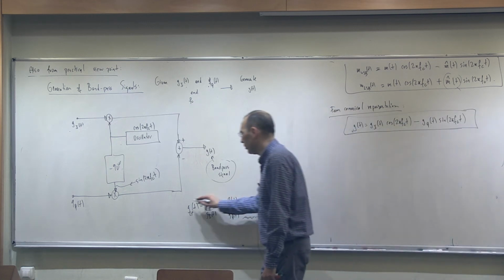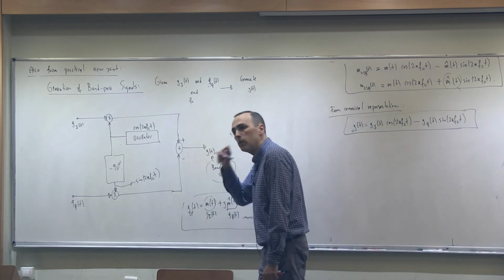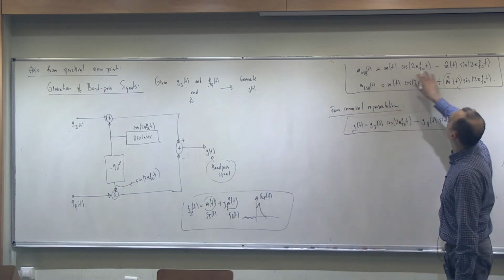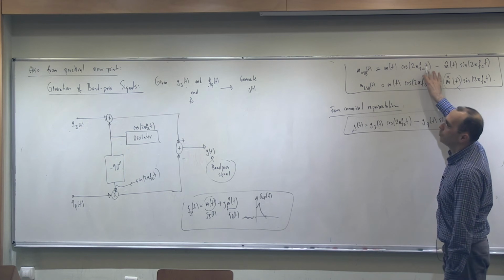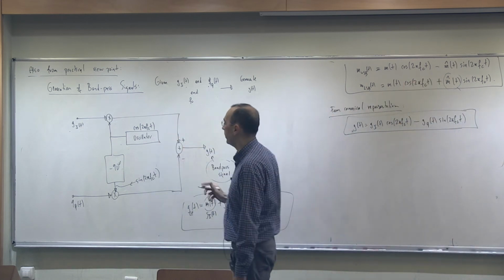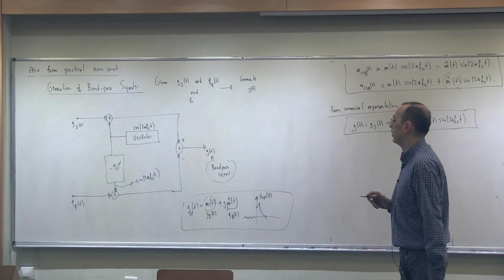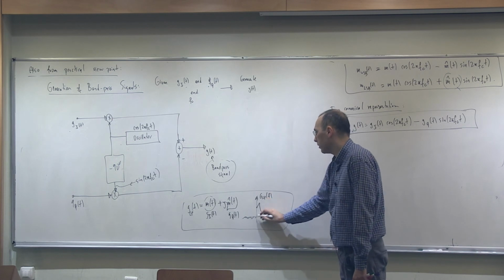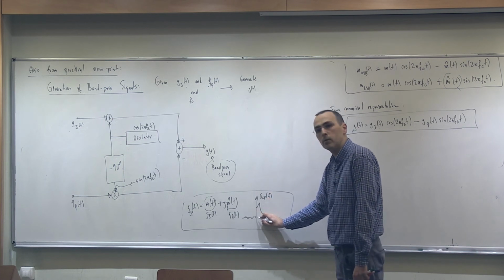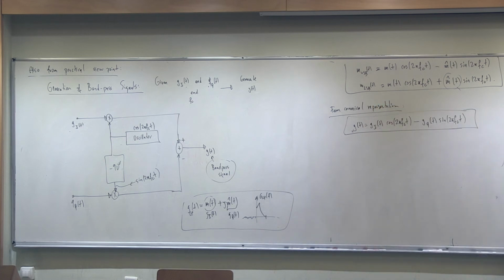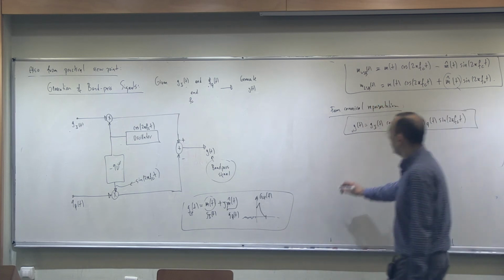Okay, this is just a note. This is the thing that we didn't prove. Do you remember I was telling you at the beginning of this hour that we can prove this by Fourier transforms, but we don't need to prove it by Fourier transforms? Now we have studied this bandpass signal representation. So I know that if I have a low-pass equivalent like that, it will be something like this with negative frequencies all 0. So if you shift this, clearly this is upper sideband. That is it.